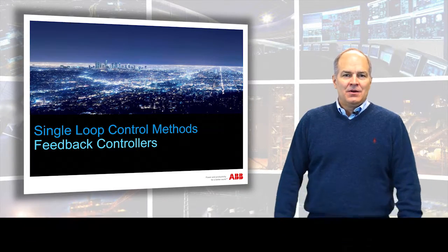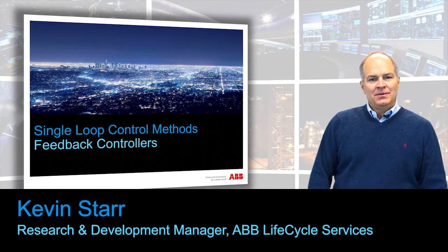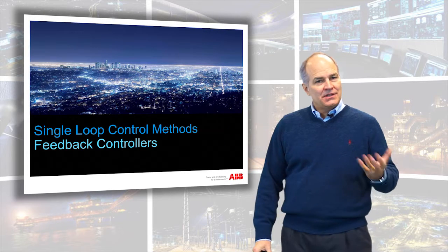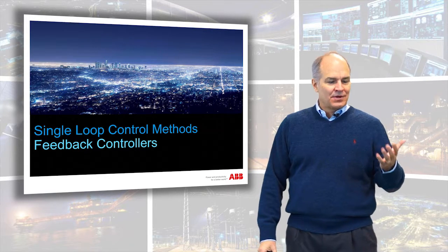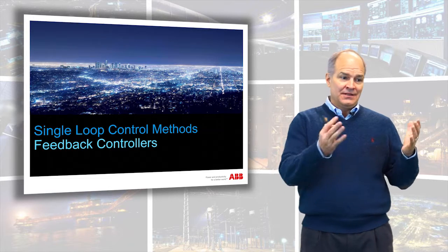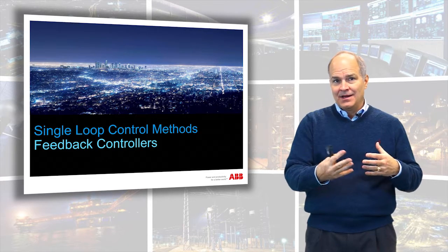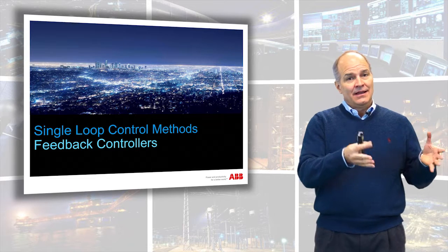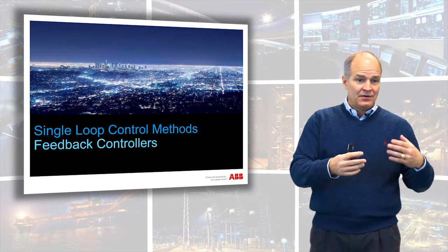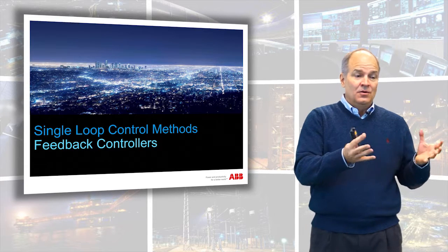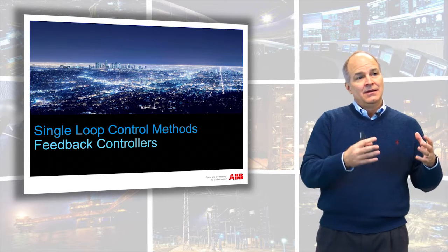Hi everyone, we're almost ready to get into tuning, but before we get into tuning we need to understand the controller. We just got done talking about the process. The process is essential. You have to identify the characteristics of the process: gains, time constants, type of process. That's important. Whether you walk and look at it or do a bump test or do Newton's laws of physics, you have to calculate or determine what you're working with.